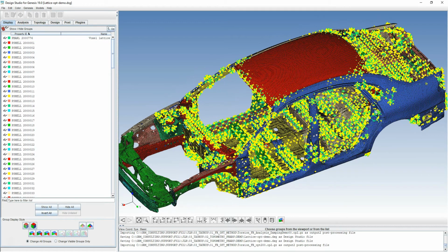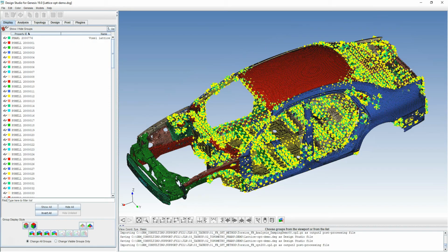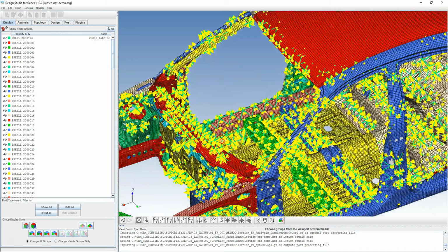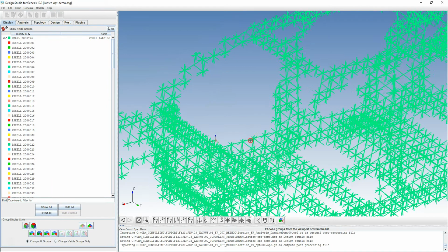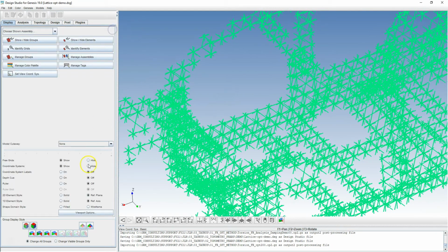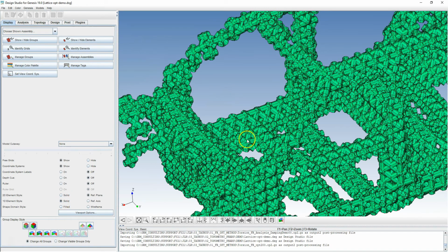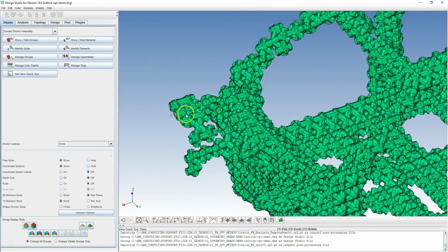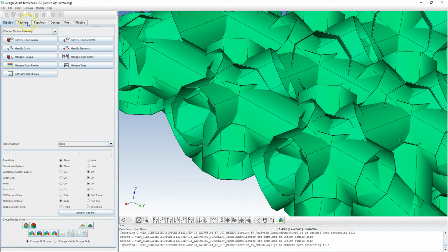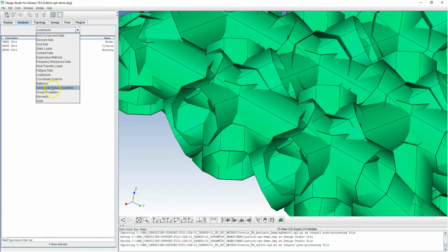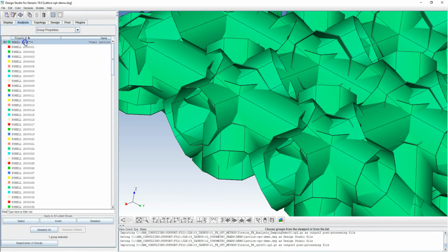So we've got an example for torus, and for this example we've used the Lattice mesh generation tool to create orthogonal lattices. We have just one property, so I can actually show only these on screen now. And if I view these in 1D style, you'll see if I zoom in, they are tubes. And there's the cross section that we have in place. And I can take a look at those inside the group properties menu, PBARL.